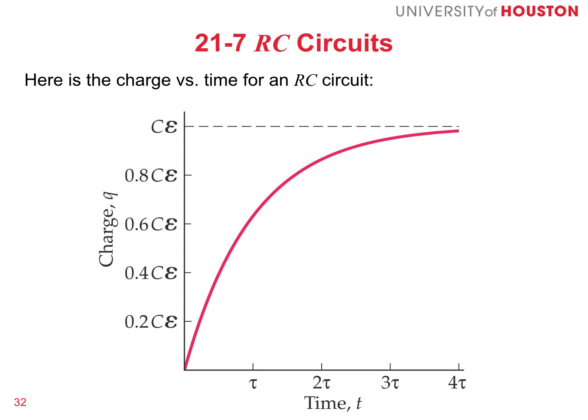At small times, the rate of charge, which is the amount of extra charge on the capacitor per unit of time, is rather large, and as time goes on, this rate will decrease until it becomes zero at a very long time, where the charge on the capacitor will eventually be the capacitance times the EMF, which is shown by this dashed line.